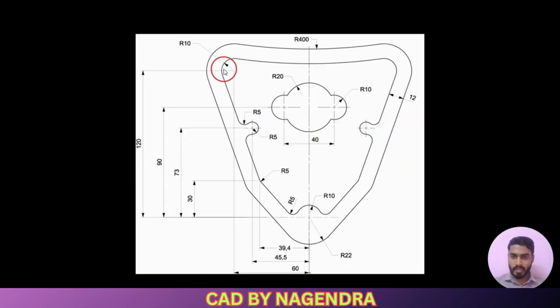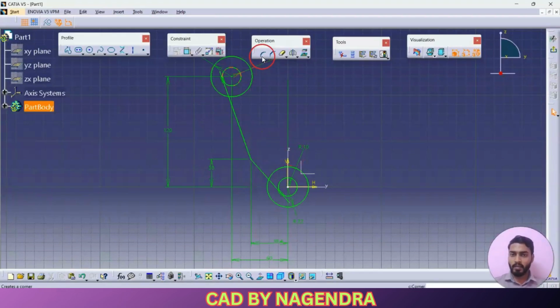Next, the same shape we have outside with a distance of 12. Before making this offset, we will apply a corner radius of 5. Let me apply Corner here. We don't want any extra elements, so we'll go with trim all elements between this and this, in this direction, with radius of 5.